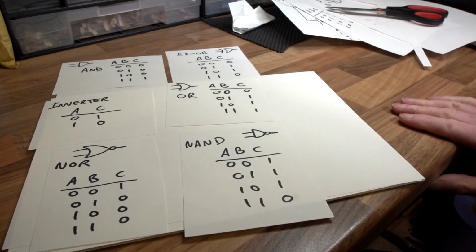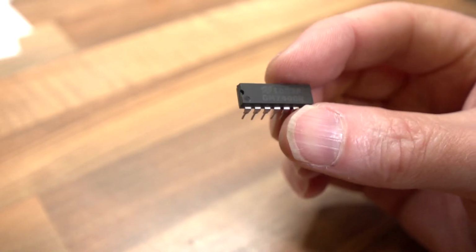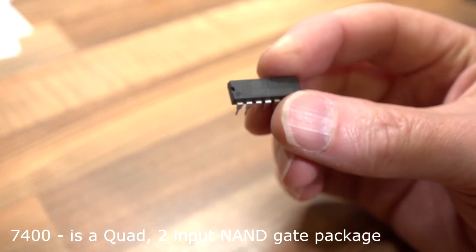So now let's actually try a few gates in practice, and we'll put some chips on a board with some LEDs and that kind of thing, and see how they work. Here's a typical example. This is an integrated circuit, a chip, and this particular one has NAND gates in it. It actually has 4 NAND gates in a single package, what we call a package or a chip.